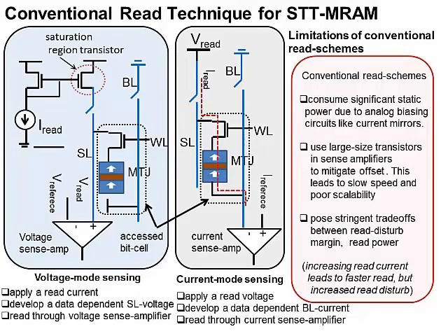Now, if you look at the conventional MRAM sensing scheme, the two most common methods are voltage mode or current mode. In the first scheme, the current mode scheme, we can inject a constant current across this resistive memory cell, and the voltage developed across it can be sensed using a voltage sense amplifier. A complementary method is to apply a constant voltage and sense the current generated through the resistive memory using a current sense amplifier. Both these methods use sense amplifiers, which are analog circuits, and they are significantly complex in terms of area, and they consume quite a good amount of power.